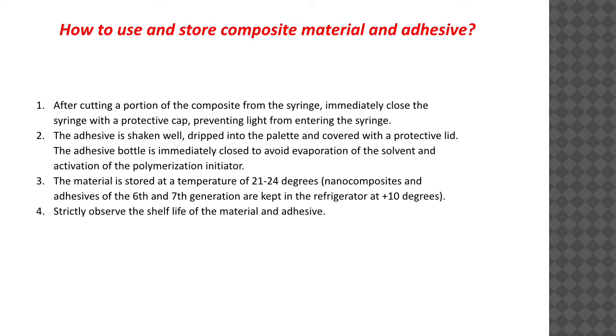The material is stored at a temperature of 21 to 24 degrees, but nanocomposites and adhesive of the 6th and the 7th generations are kept in the refrigerator at plus 10 degrees Celsius. Strictly observe the shelf life of the material and adhesive and do not use it if the due date is over.